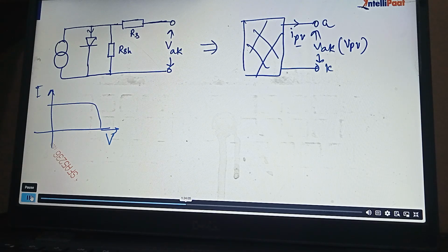Okay. But instead of using a diode over here, we can straight away use a resistance, as you can see in the diagram, where a resistance has been used. Why do you need the diode here, sir? Because it is a semiconductor material. It will have an anode and cathode, a photodiode. How will a resistance generate the power? Let me tell you, this resistance will not have any depletion region where the electrons can cross the depletion region, combine, and current can start flowing. That happens only in semiconductor material.